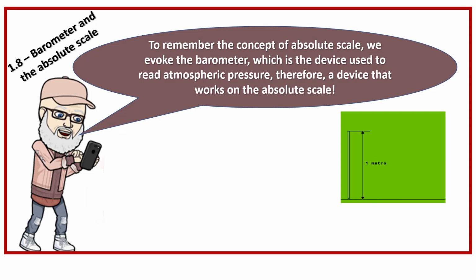We completely fill the beaker with mercury and this allows us to state that there is no air in the beaker. Then we put mercury in the reservoir and it has a free surface, that is, it is subject to atmospheric pressure. Then we capsize the beaker in the reservoir and observe that the mercury drops to the 76 centimeters level and there it remains in equilibrium.